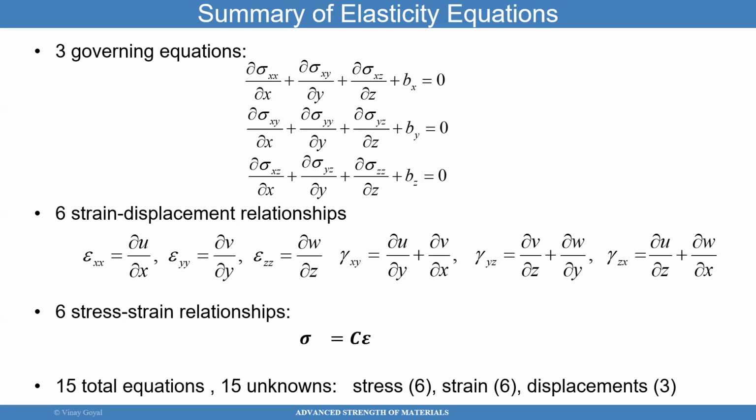For example, an aircraft could have small rivet holes, and you don't want to model every little rivet hole in the finite element model because that will be computationally expensive. But yet you can maybe come up with the far field stresses and use the far field stresses to enable you to use hand calculations to then estimate the stresses near the rivet hole.